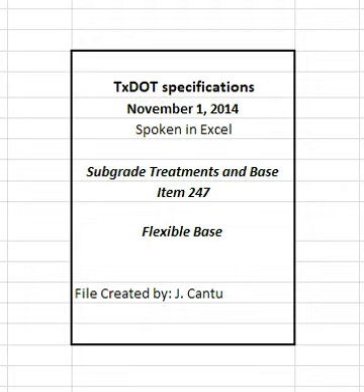2.1.2.4 Type D Type A material or crushed concrete. Crushed concrete containing gravel will be considered Type D material. Crushed concrete must meet the requirements in Section 247.2.1.3.2, recycled material, including crushed concrete, requirements, and be managed in a way to provide for uniform quality. The engineer may require separate dedicated stockpiles in order to verify compliance.